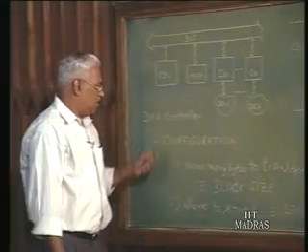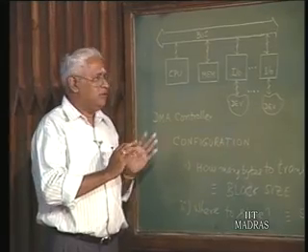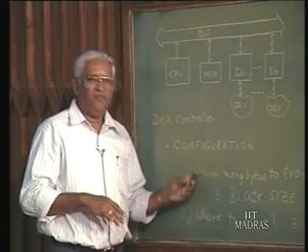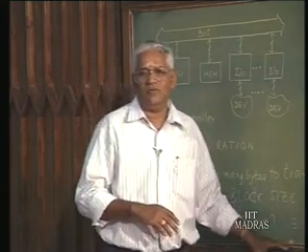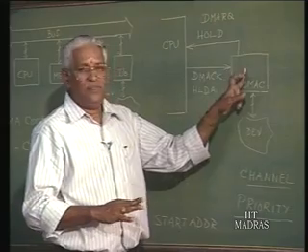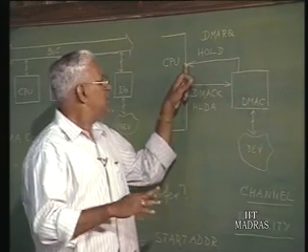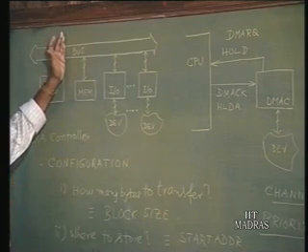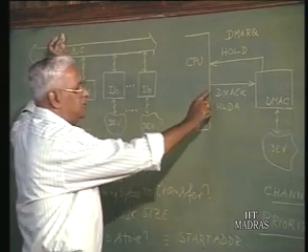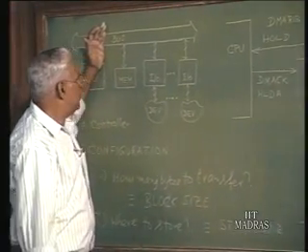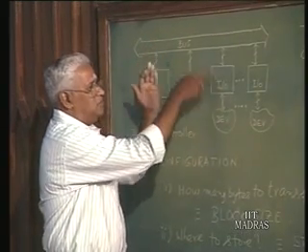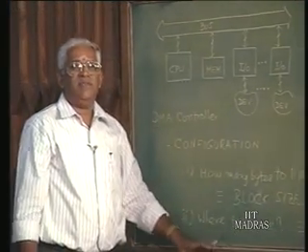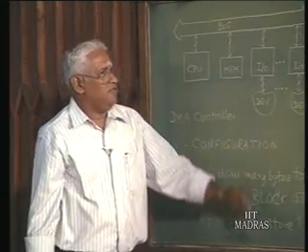Now, getting back to the program that is needed. So, the DMA controller is set up by the CPU with the issue of these bits of information, and that is part of the whole show. Afterwards, when the device is ready, the DMA controller will indicate to the CPU it is ready. Then the CPU at a convenient time, I had mentioned earlier what is a convenient time, at a convenient time, it will stop processing, and then it will generate the acknowledge. On seeing the acknowledgement, okay, the device will start doing the data transfer between the device and the memory. That is why it is also called direct memory access. Directly the memory is accessed, or the DMA, right. Good. This is as far as the data transfer is concerned.